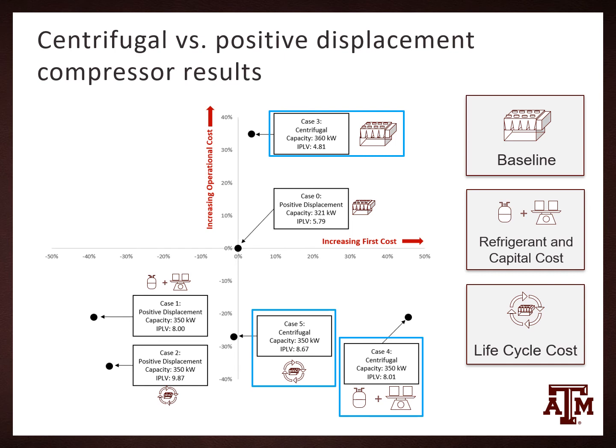Using the mapped heat exchangers, these thermoeconomic comparisons between different chiller configurations were possible. From this study, it can be concluded that the use of a positive displacement compressor will be more advantageous when the lifecycle cost of the chiller is optimized using the heat exchanger geometry variables.